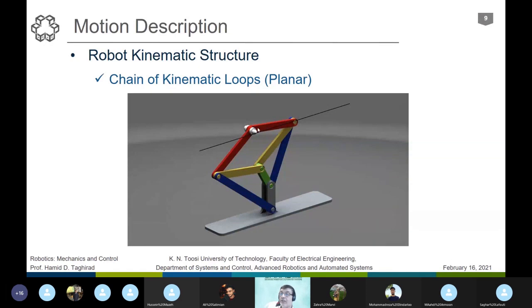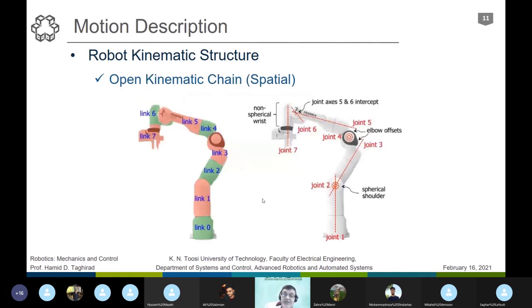But if you have a serial manipulator and you don't have an actuator at the point, you lose the motion there. The actuation, the joint is not usable there. In a serial manipulator, the number of joints and the number of actuators are the same. In case of a closed loop system, we may have a smaller number of actuators. Sure. How reliable or controllable the system is, or how much we can determine its characteristics or its spatial characteristics?